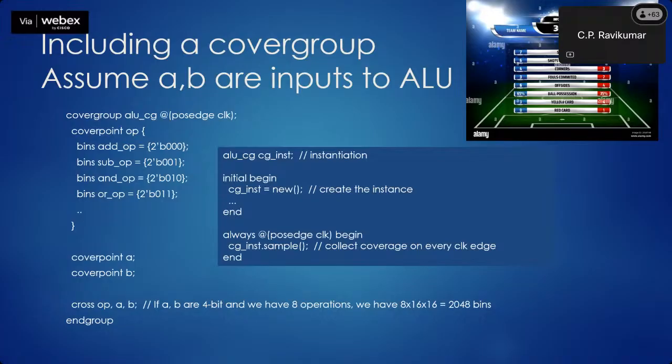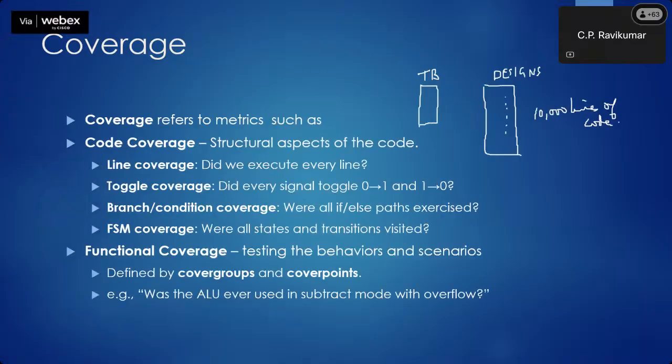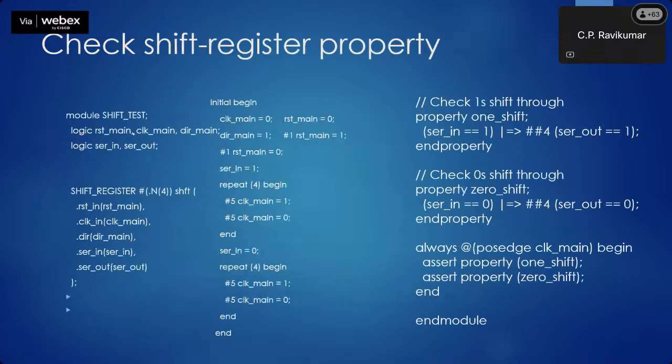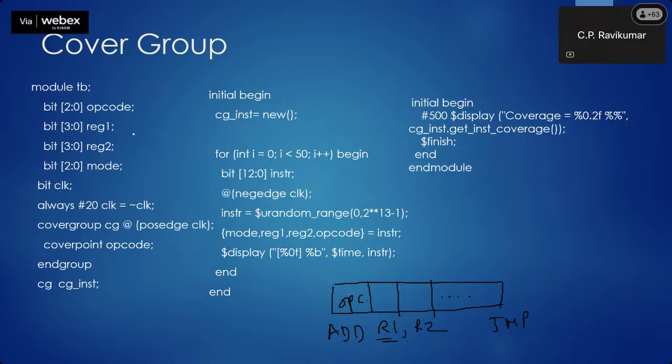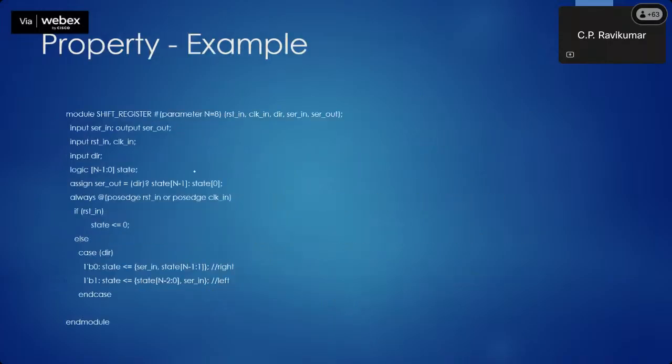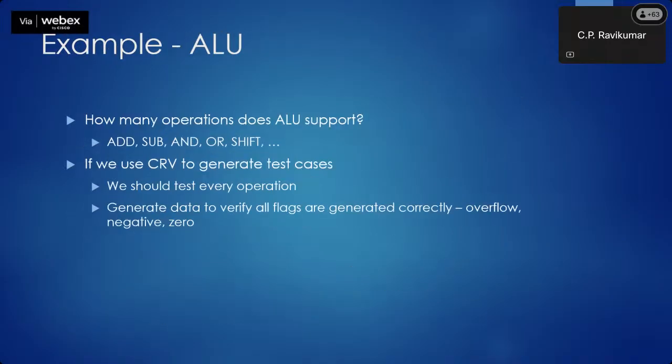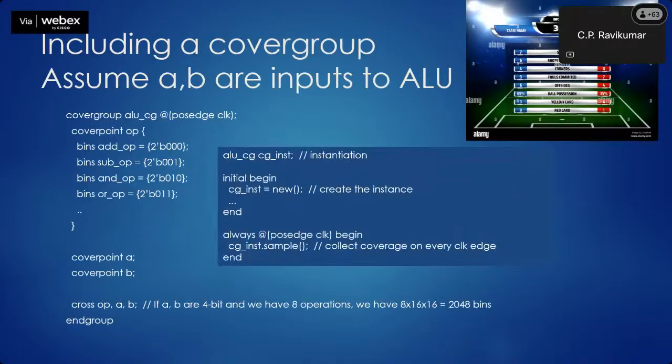In the earlier example, I was just telling you whether each opcode was tested or not. I was happy if every opcode was tested, and if every register was tested. But now that is not enough. We are in fact asking the tool to separately tell me how many times the add operator was done, how many times the subtract operator was done, etc.